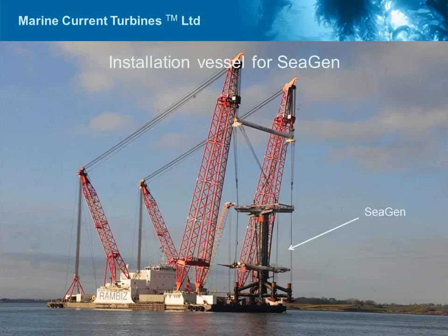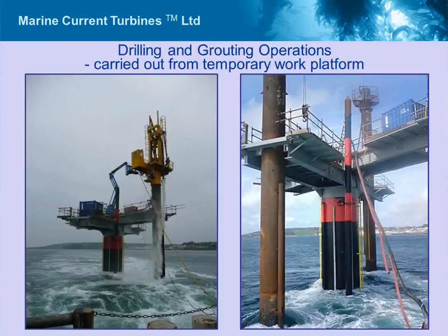The system was actually installed on the 1st of April 2008, and it was installed using what is probably the world's largest crane barge. There's not too many of these assets in the world, so if you design your installation process, don't design it around using these crane barges because it's not a good idea. The whole positioning of SeaGen on the seabed went bang on. It was actually positioned within 10 centimeters of the target location, and that was a good job because we had pre-installed the power cable to the structure. Next slide, please.